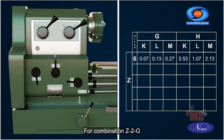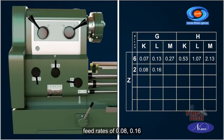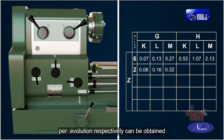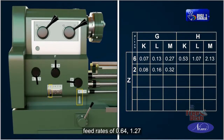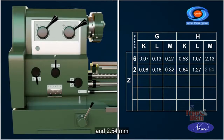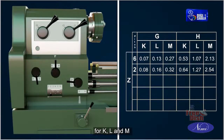For combination Z2G feed rates of 0.08, 0.16 and 0.32 mm per revolution respectively can be obtained for K, L and M. Similarly, for the combination of Z2H feed rates of 0.64, 1.27 and 2.54 mm per revolution respectively can be obtained for K, L and M.